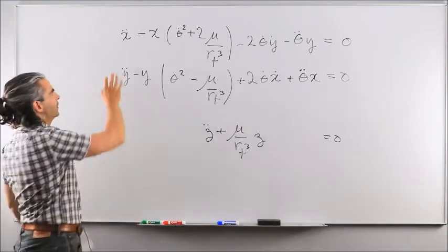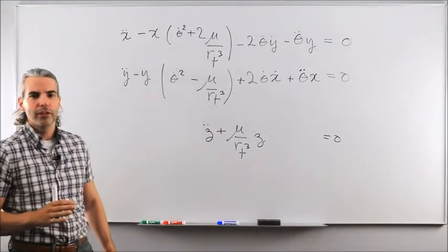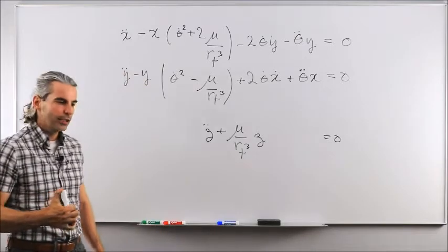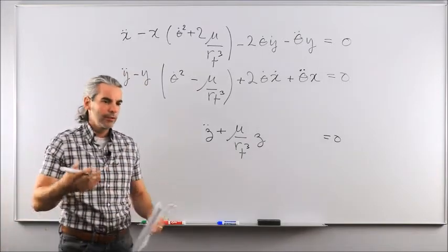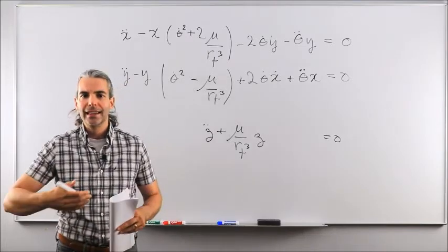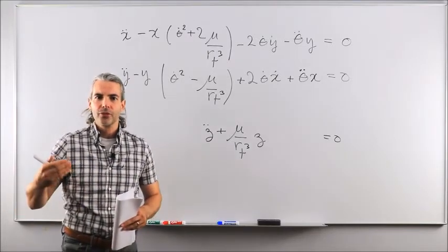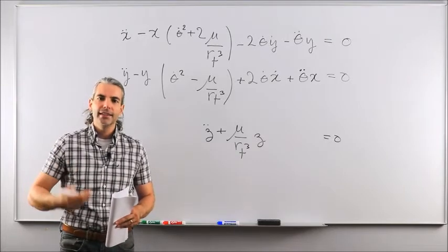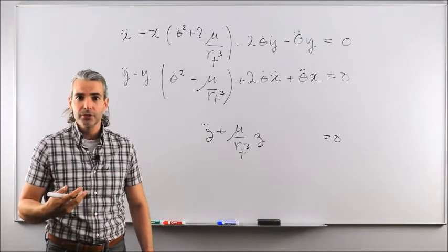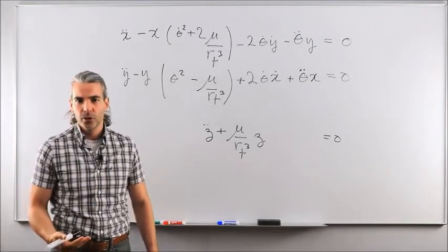Okay, so last time, if you remember what we did in terms of formation flying, we had derived exact nonlinear equations of relative motion. And then we said, well, those are very accurate. Yes, it's good, but we're not able to obtain analytical expressions for the x, y, and z components as function of time. In order to achieve this, we needed to linearize the equations of motion.